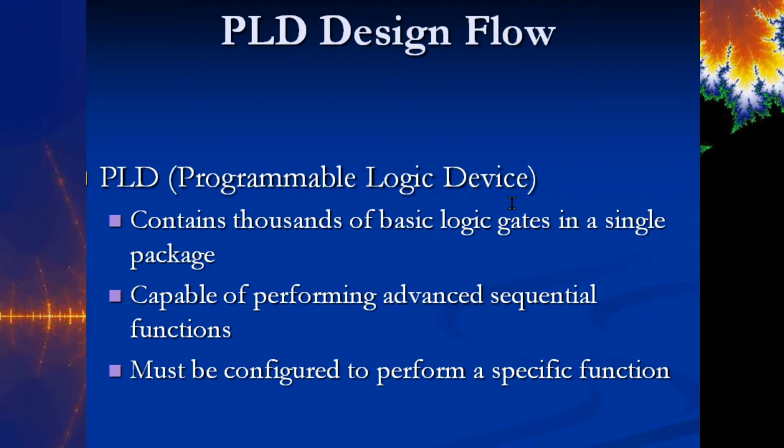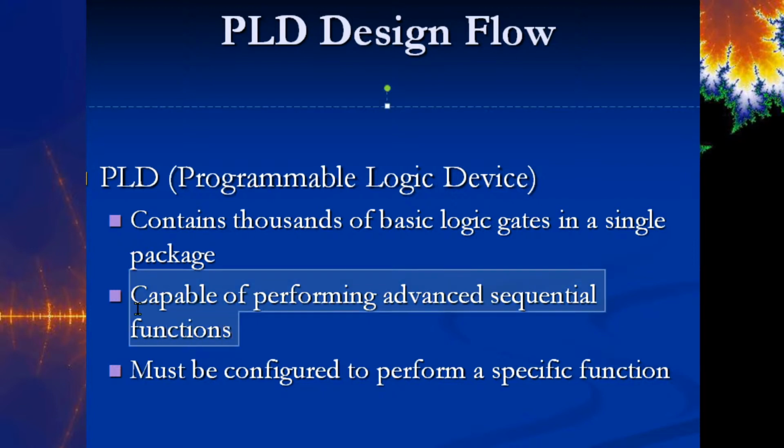And when you create your VHDL file or when you create your BDF file, essentially you're telling it what to do. You're saying grab a few of these gates that you have here and make these connections internally. So that's what it does. You download your program, it makes the internal connections, it takes the inputs to the switches and takes the outputs to the LEDs or the 7-segment displays or whatever. And so it does it all automatically.